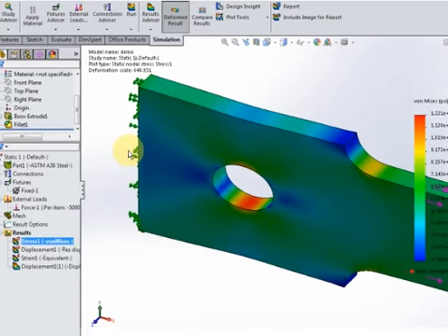The other factor that would happen with one of these wooden trusses that we're building is that this method is not even going to be able to do it without us actually introducing a whole other set of tools that SolidWorks has. This is not going to evaluate buckling. That's a whole other kind of analysis that it's not doing in this setup.